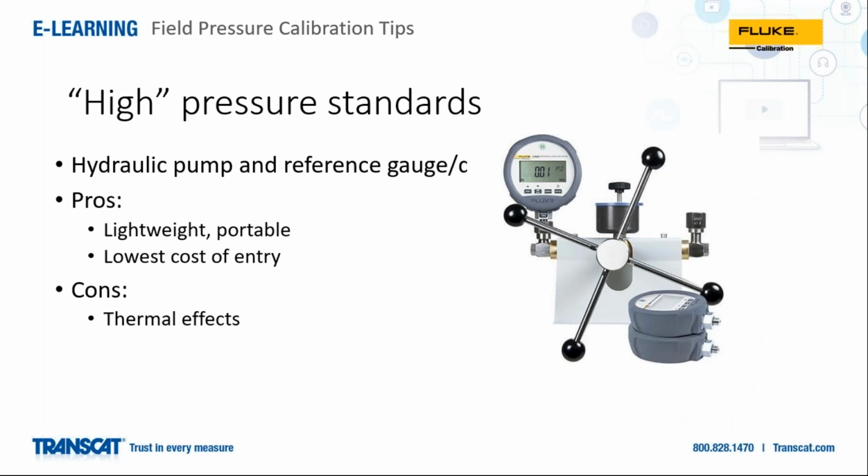Another type of system here is a hydraulic pump and reference gauge combination. Again, this is lightweight, portable, lowest cost of entry. So these are relatively inexpensive as calibration standards go. Again, it's a sealed system. So again, thermal effects have to be thought of and dealt with.